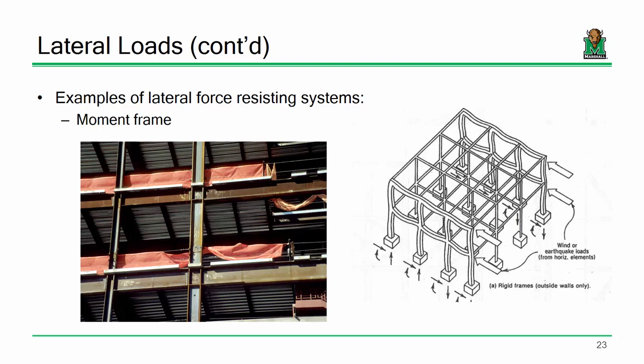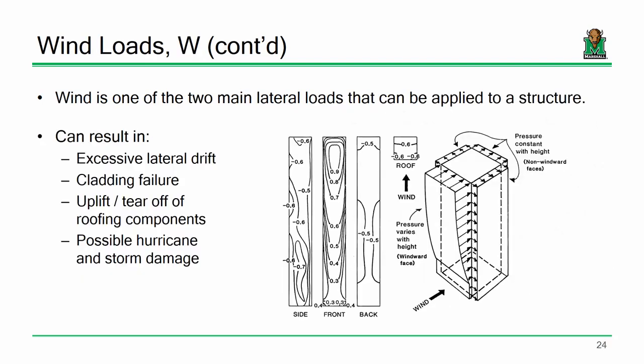All right. We're starting to get close to where we should probably call it. What we're going to do next time is start to discuss the primary load effects that happen laterally on structures, particularly wind and seismic. Wind can get a little complicated because wind pressures increase the taller the building gets, so you have to address that in some fashion or another. And then earthquakes can get a little complicated because they don't even load the building, they accelerate the building. So you have to break out some force equals mass times acceleration stuff and all of that.